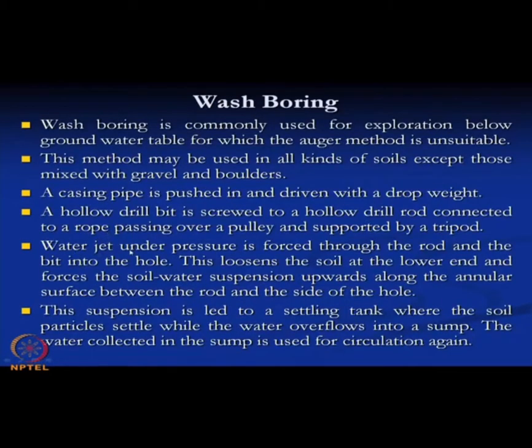and the water jet under pressure is forced through the rod and bit into the hole, and therefore this water jet loosens the soil at the lower end and forces the soil-water suspension upward along the annular space between the rod and the side of the hole, and this suspension is then collected in a settling tank where soil particles settle, and the water overflows from the tank and the water collected in the sump is used for circulation again.